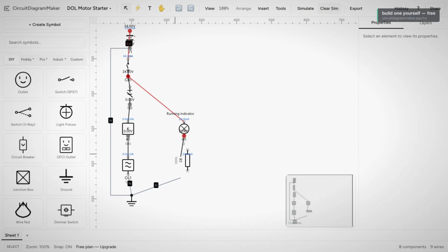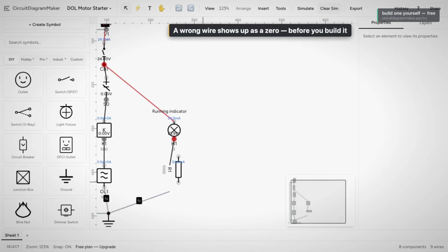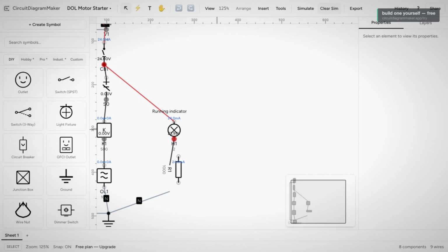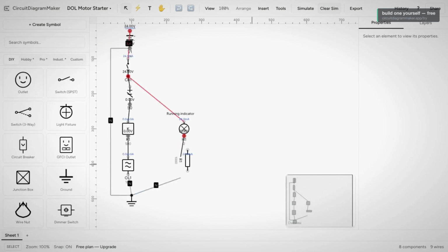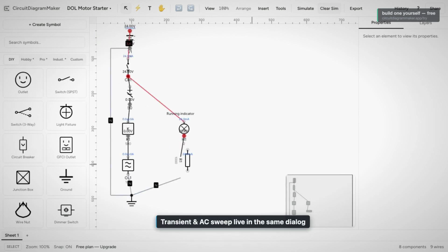Now the step that sets this apart from a plain drawing: we simulate to prove it works. There's a real SPICE engine built into the page. The same kind of simulation math that professional electronics tools use. Open Simulate, choose DC operating point, and hit Run. Live voltages and currents appear right on the diagram. Real numbers computed from the exact wiring you drew, not a canned animation.